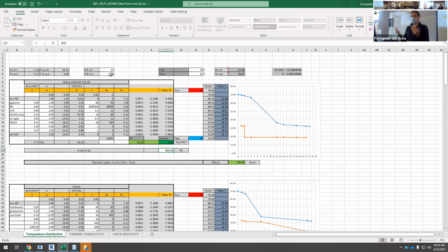And have I done something wrong? At the beginning, we had done something wrong with REVIT. We didn't have thermal insulation on the floor. We have a wall with a very low R value. Okay, by looking at this and then REVIT, we found out that there was something wrong. There was a mistake. Okay, let's fix the mistake. It's still, they don't match, these two figures.